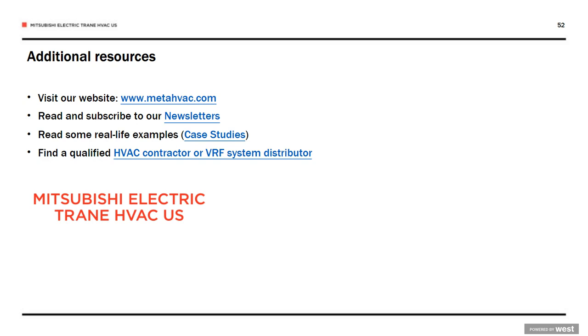So, yes, you should have thermal setbacks. Let's say it's 6 to 8 degrees setbacks, which is fine. You'll save a lot of energy, and then you start up your system in the morning, early morning warm up, and then you just let the VRF system run. So you should use setbacks because it saves a lot of money when people are not in the building.